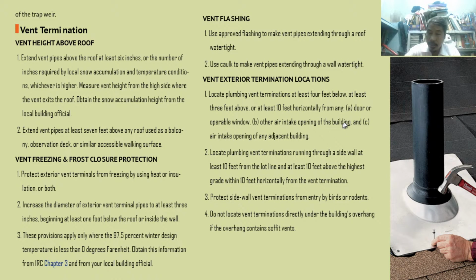Up to the adjacent building. So, for example, you have a door, okay, and then you will install the vent. So we need a horizontal distance from the door of about 10 feet. Okay, 10 feet horizontal distance.